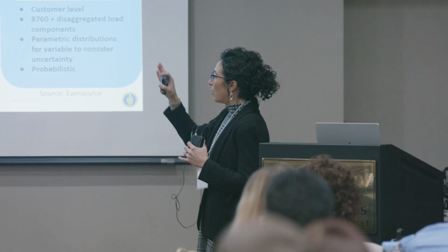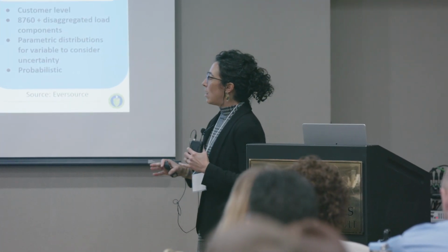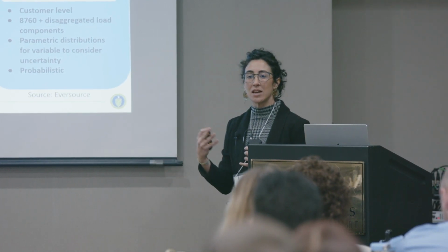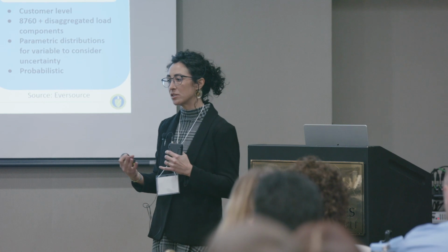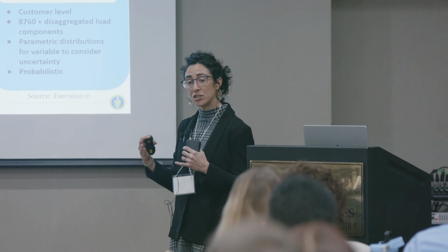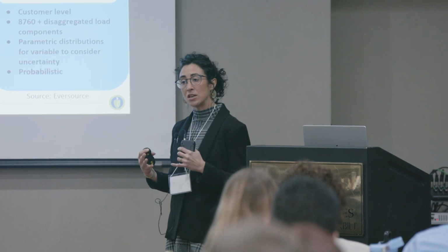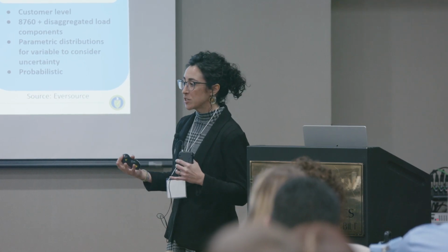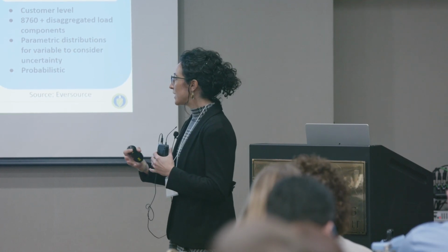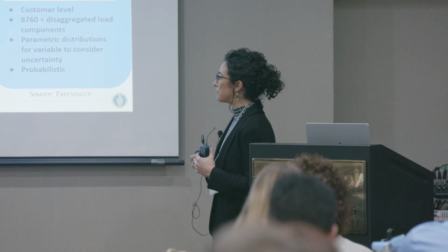So where most of them are is that they look at a 5-year time horizon. They use economic trends to forecast the future, so demographics, economics. They might start to do some DER adjustments to that forecast. So how much PV did I have? Might I adjust a little bit the peaks in my circuits for DRs?